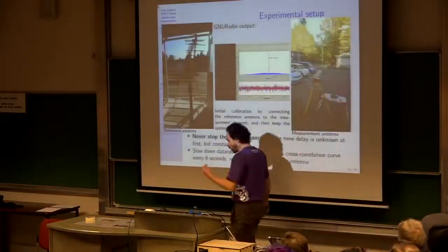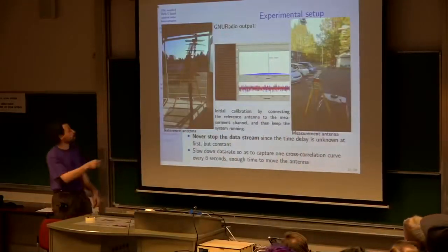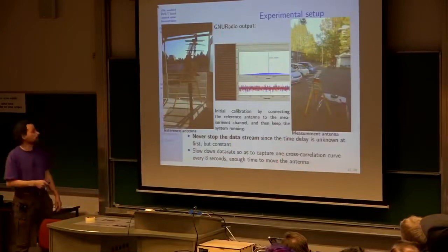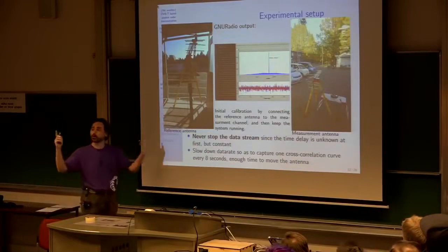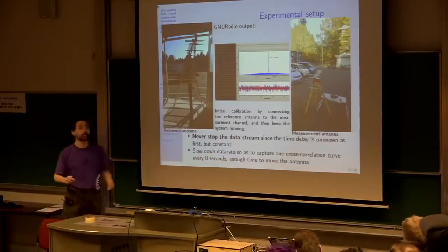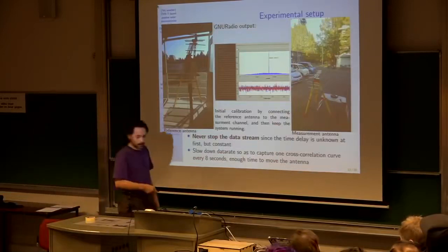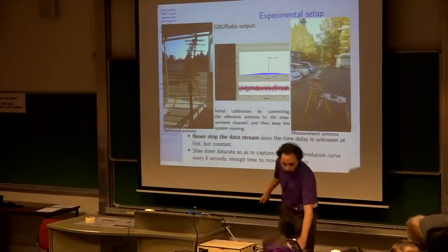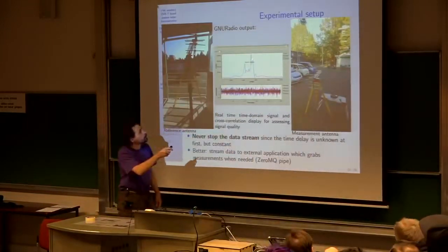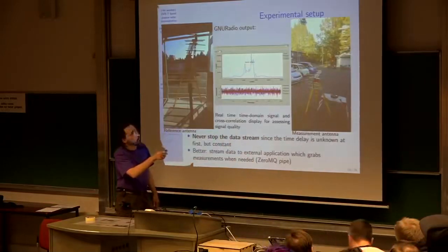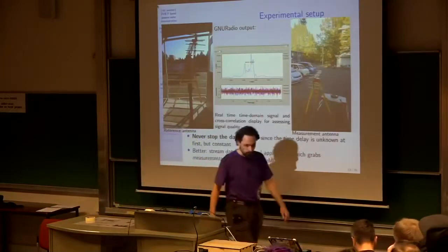So that's the actual setup. The actual setup is 1 antenna facing towards the target, 1 antenna facing towards the DVB-T receivers. We run the flow graph. We have a cross-correlation peak. So the 2 data streams are contiguous and continuous, and we do have a proper operation. If we zoom into this peak here, we do see some structure, which is quite encouraging. So we do see the correlation peak here, the 0 time, and we see all these familiar structures, which are, I will show you, target reflections. So that's a good start.